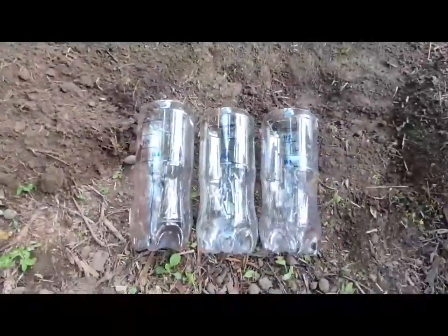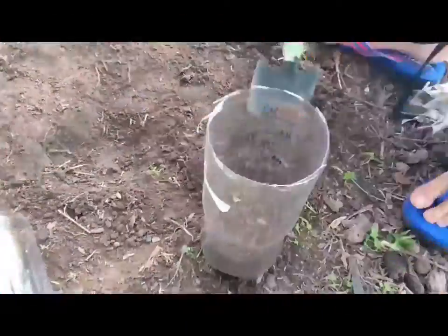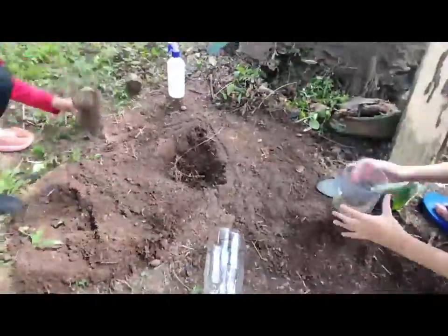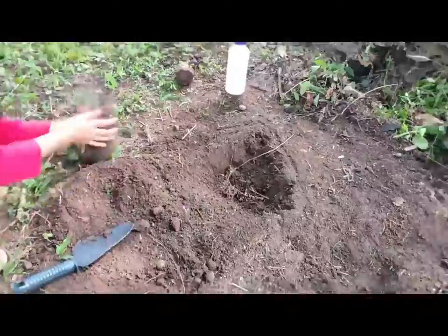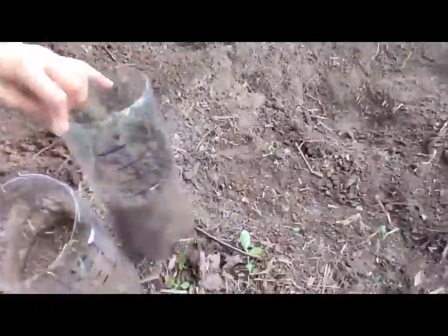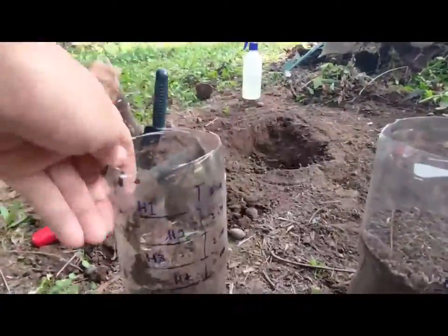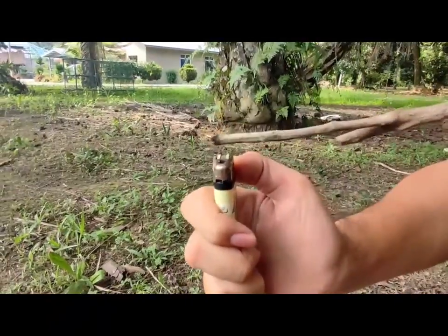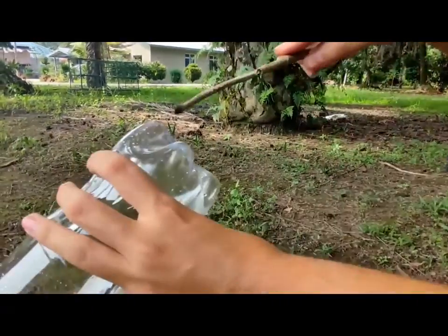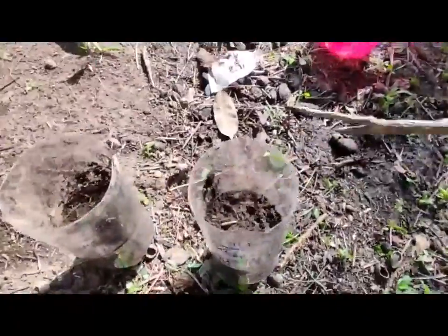For the permeability test procedure, firstly we will acquire a soil sample from site. The soil sample is not to be disturbed, or as we call it, in undisturbed condition, and then we will prepare the cylinder container with drainage at the bottom. The next step is to fill the container with the soil sample, and then mark the lines H1, H2, H3 until H4 on the cylinder container.